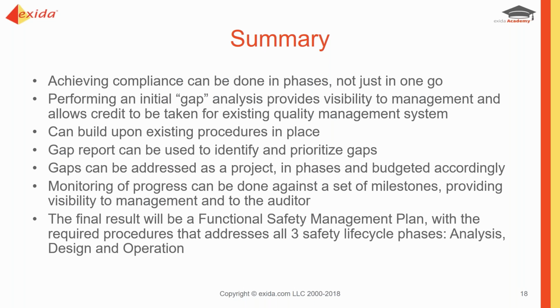So what we get out of this ultimately is a functional safety management plan, which is the first requirement for compliance with 61511. We will meet clause 5. So we make sure then that we have the required procedures that address all 3 life cycle phases.